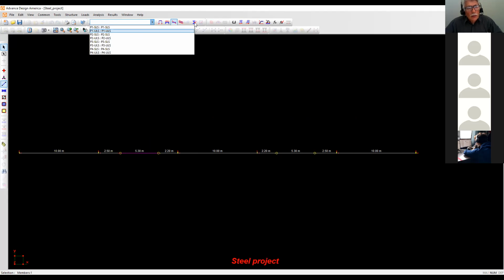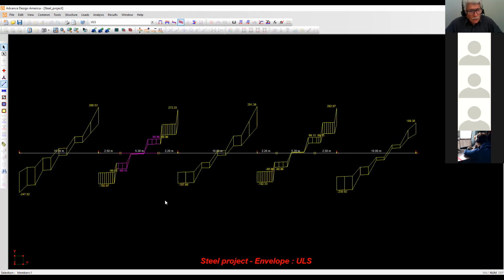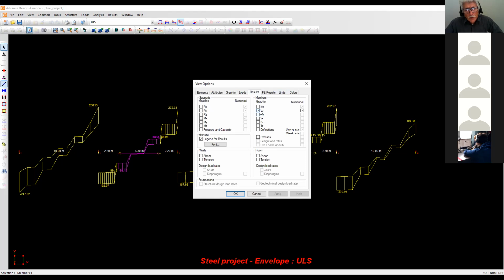Okay, so now I want to look at your envelope first of all. Let me look at the strength. So there's your shears. I don't remember the results, Nermin, so I don't know if it's good or not. But what do you mean, like the first one's acting as a cantilever? Let me go look at your moments. Oops, sorry, save. Let me go look at your moments results. Take this off. Let me look at MX. Okay, apply.